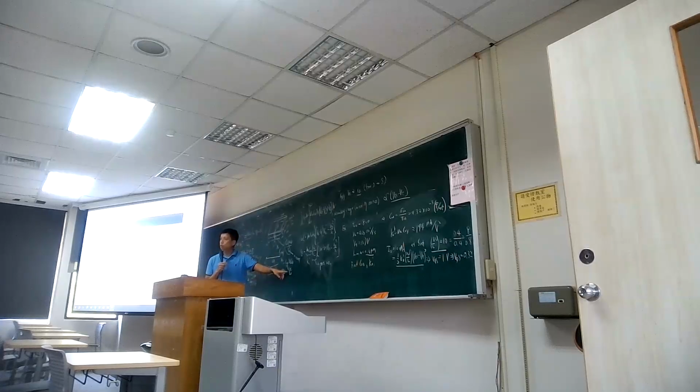Okay, so why do we use high-K? Because if you consider the oxide, high-K material means the epsilon is larger than the oxide, typically 2 to 3 times larger. You just replace it with high-K without changing any lithography, any dimension. You just boost up the current by 2 times or even 3 times, 3 generations. That means you can play with this material for one year and then take your bonus for 3 years, right? Without changing lithography, without changing pattern. That's the power of material.